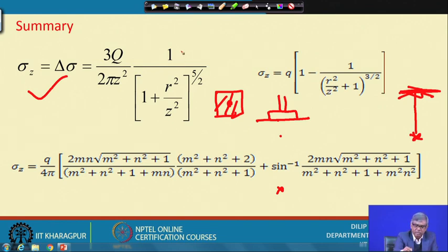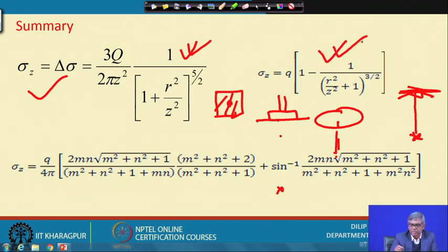So, this same formula can be utilized, and if a circular foundation is loaded, then I can integrate and find out, along the center line of the footing at different depths, what the pressure variation is. By integration I can find out this expression. This expression also is important to remember, and you can find out at different depths what the pressure is along the center line of the footing.